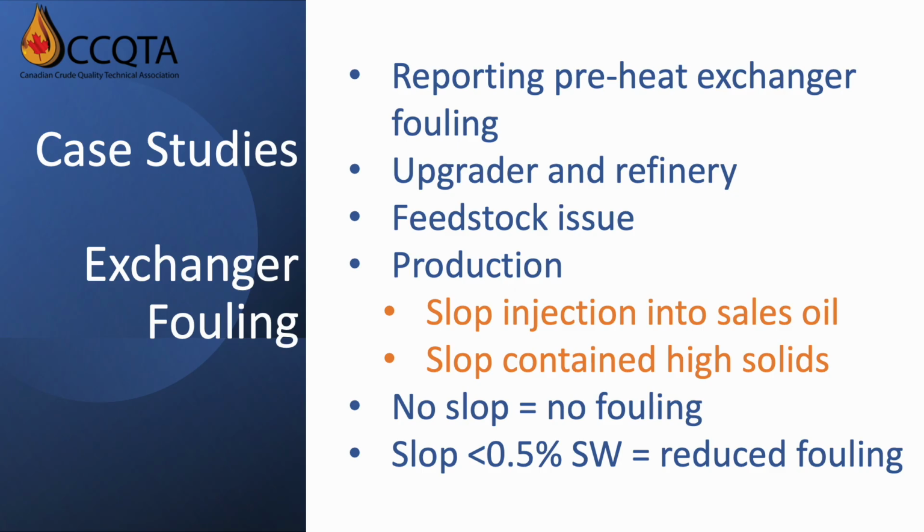It's also a cautionary tale for production slop handling, which may be one of the sources of high solids excursions we talked about earlier. Although slop may appear harmless because the volume is low relative to production, it may also have unintended consequences.